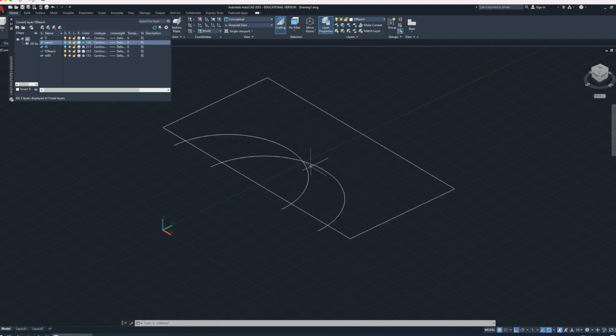Okay, and now you can see I've got my reach limits here, and I've got the rectangle indicating the footprint of the bench. I don't need these parts sticking out here from the edge of the bench, so I'm going to use trim. And I can just go along and cut these off. They're kind of a nuisance. They look like something you're going to get poked on. Okay, so there's the bench with the top of the reach. So let's put some dimensions on this.